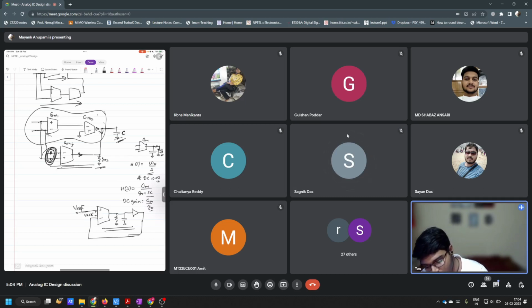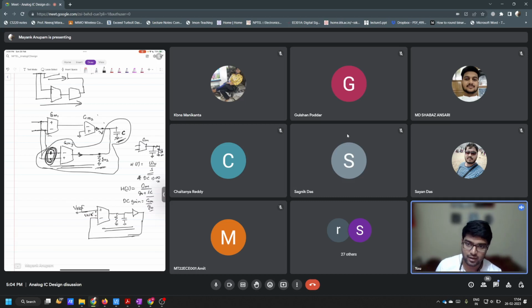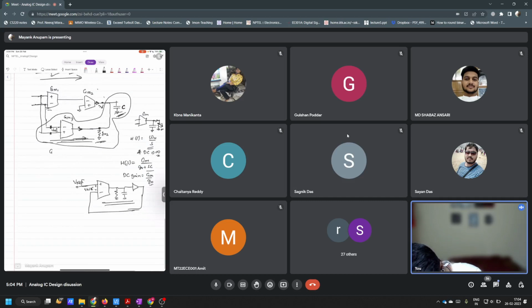So what we can do is, once this op amp here has reached its steady state, that means it has already done all the comparison, and there is some finite error here. After that, what do I want to make sure? That this error is again reduced. And how will I do that? How will this error be reduced? If you do not know anything about the transconductor, you know that for a transconductor this equation has to be satisfied: GMF here times V error has to be equal to what? This current, right? GO2 times whatever current is flowing inside.